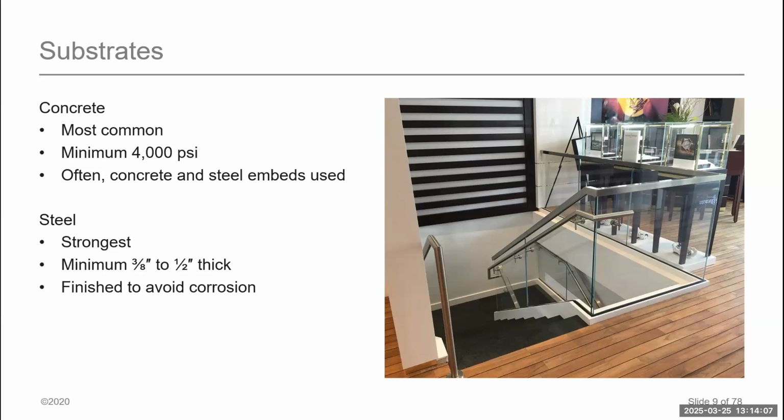When we start talking about base clamps and adapters, one of the things we have with those is the anchoring is not as frequent. So we will see a larger load transfer to the anchor itself. And we will need an embed of anywhere from 5 to 6 inches into the concrete with an anchor that is for a base shoe. Or if we're going fascia mount with an adapter that we'll talk about later, we're going to need somewhere between 5 and 6 inches of embed.